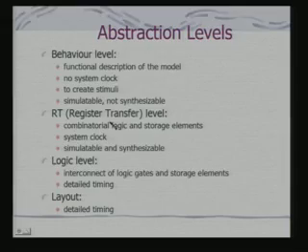Next, from the behavior level we come to what is called the register transfer level. At the register transfer level, we specify the activity in terms of combinational logic and storage elements. We specify the system clock, because the storage elements would actually be flip flops. So, why is it register transfer? Because I can specify the behavior of the circuit in terms of data transfer between different registers, and while the data transfer takes place, the data gets modified or transformed using your combinational circuit. That is exactly how you have designed your digital circuits.